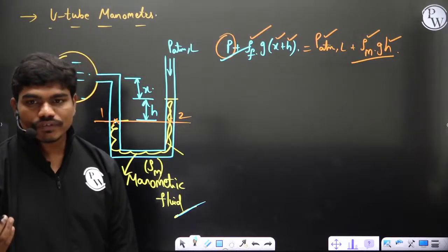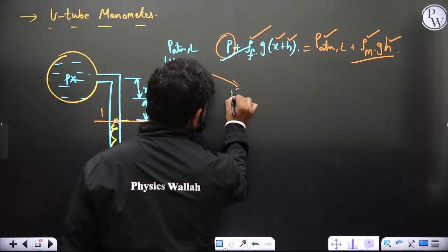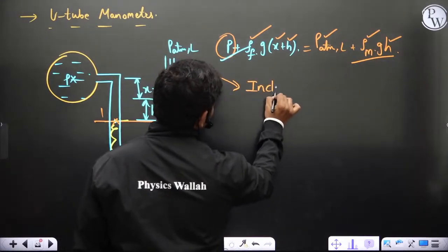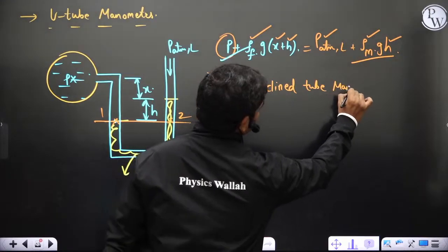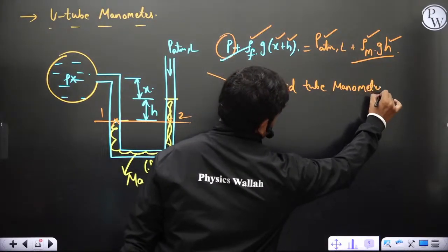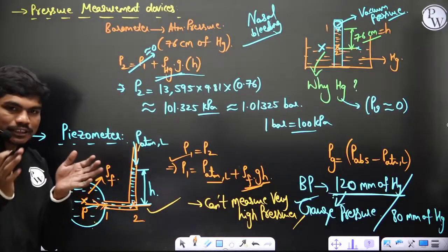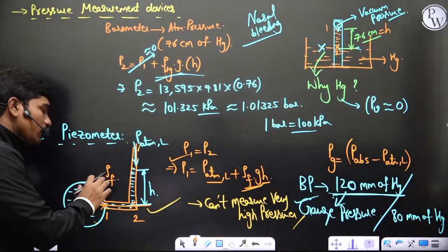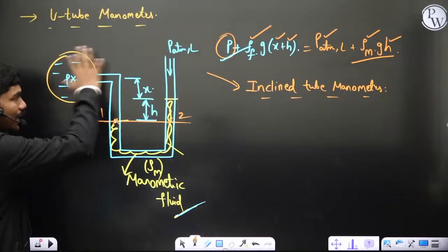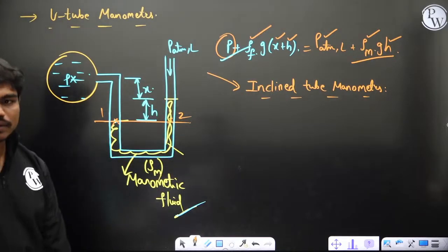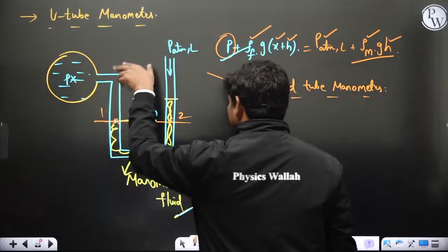Now the story of inclined tube manometers is important, because from this, the next step they felt is inclined tube manometers. So see here, in the first step, they were able to measure only certain pressure range of a particular incompressible fluids or basically liquids. But this device is not suitable for gases and all, but they eliminated all these problems in this case. Okay, like for example, even if you put a gas, this mercury will not allow the gas to escape, so you can measure the pressure difference.